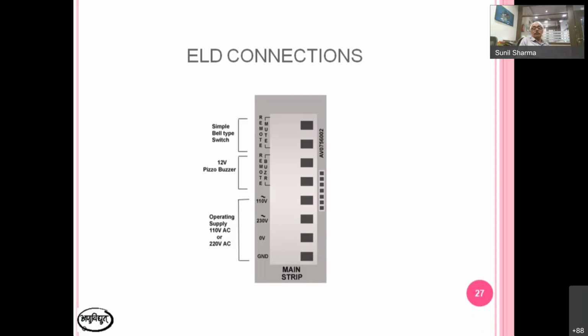So you always have problems. Again, if you have any red light and you have muted the buzzer, it sounds again as soon as the light appears. So please use 110 volt. It is not a very big load. It is about 1 ampere load for 12 channels. So please put on the 110 volt, because in 99.99 percent of cases the instruments run on 110 volt AC.